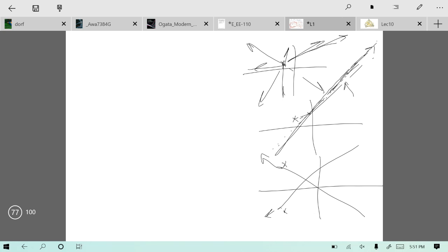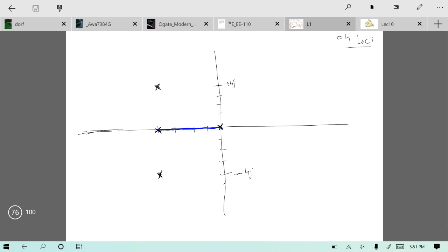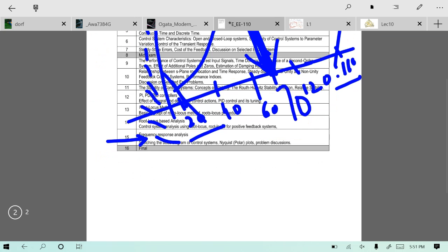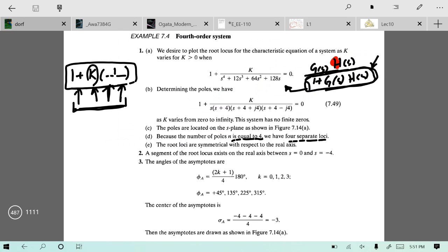So this is a part of root locus, whereas these paths are not part of root locus. These are just the asymptotes. However, whenever the path follows this road, then this becomes a part of root locus. So asymptotes are just drawing these facilitating routes with the paths that they can follow on their way to infinity. So to find the paths, you have to find the center and angle of asymptotes. Once you know the center and angle of asymptote, you can draw these lines.